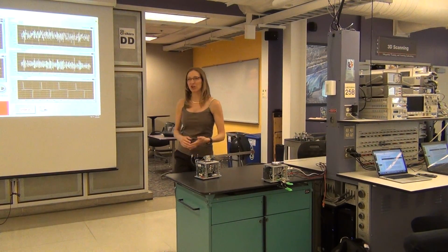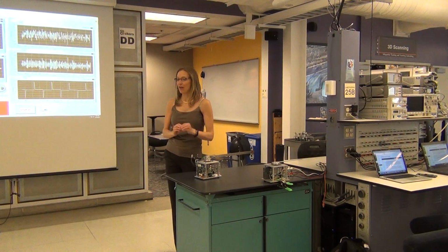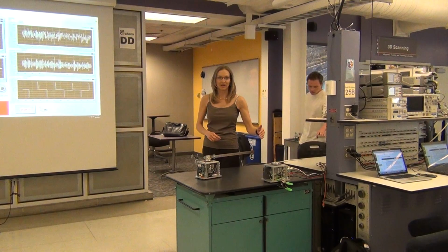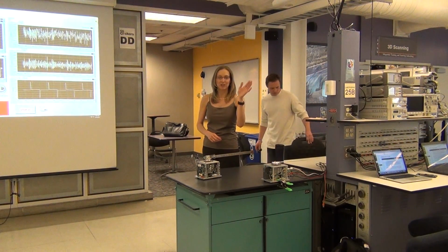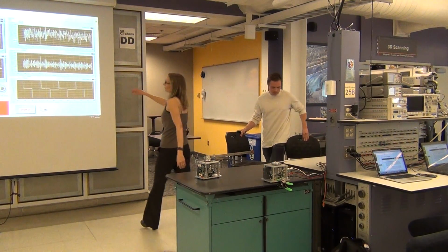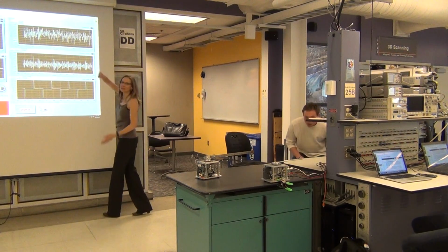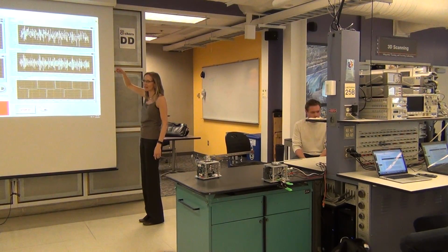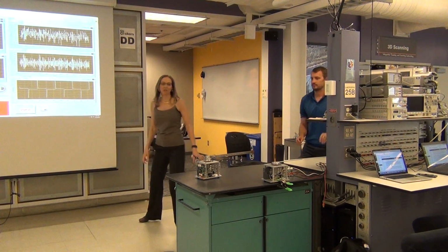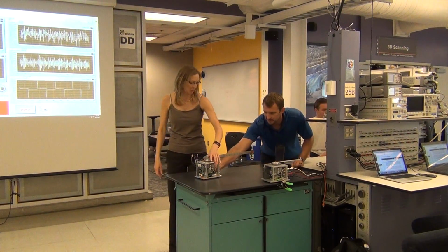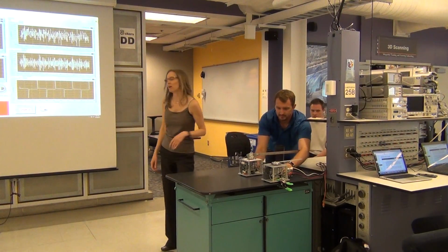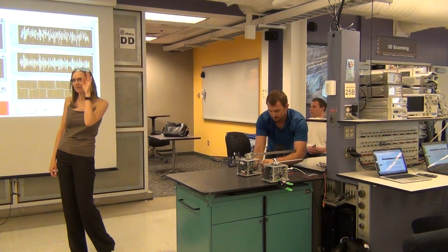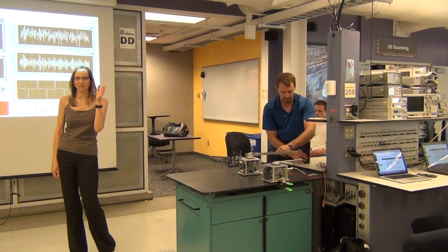Also, the strain gauges are extremely sensitive. They're so sensitive that they can actually see the little air currents of the tip as it's moving. So you'll see that this tip deflection never gets perfectly to 0. It's going to oscillate very slightly around 0. And again, we don't have enough motor voltage to overcome that slight variation in the tip deflection.